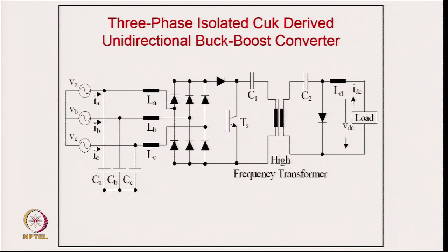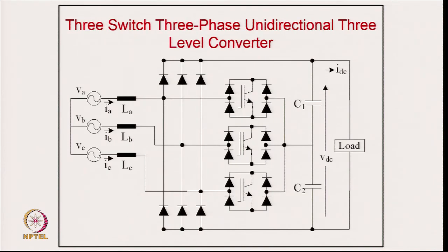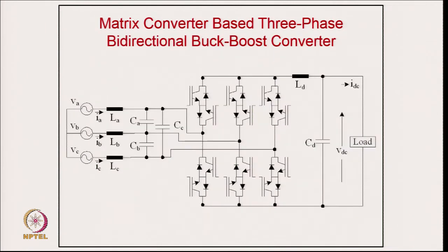And this is similar, after this you have of course the LC filter and a high frequency Cuk converter at the output, operating in DCM, typically for power factor correction converter with isolation also. And of course, this is 3 level, and you can have a multi level topology here for improving the power quality on the supply side and having a boosting operation with the help of the 3 switch bidirectional switch. This is nothing but the bidirectional switch similar to what we discussed for your Vienna rectifier, but the number of levels is increased in this case.